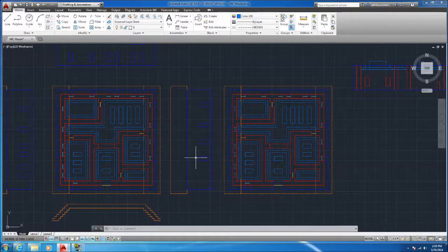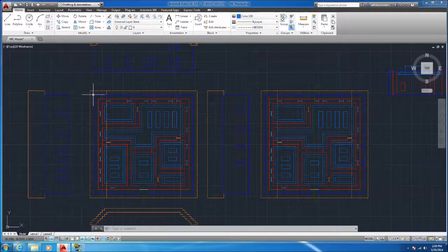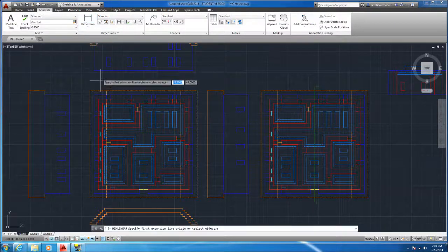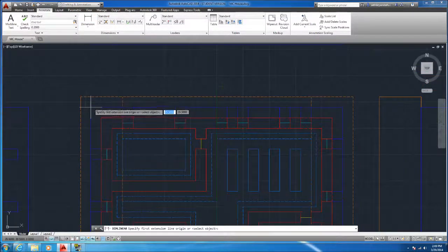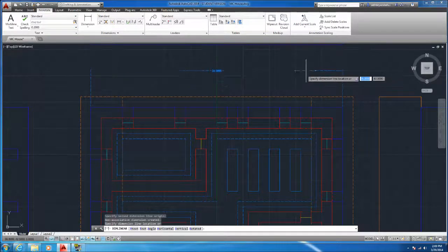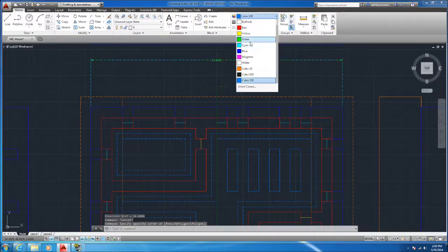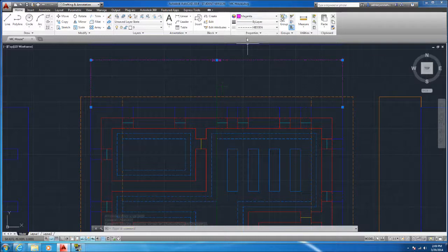And I'm actually gonna go ahead and show you guys quickly how to annotate, because you can look at this drawing and be like, wow, that looks cool, but now how do I know how to repeat it? If you go over to this third tab here, the annotate, if you click it, just hit dimension, you're gonna go from the outside edge of the exterior wall to exterior wall. Now it doesn't have to be in blue, mine just is because I didn't change the color. I'll make a magenta and make a continuous line.